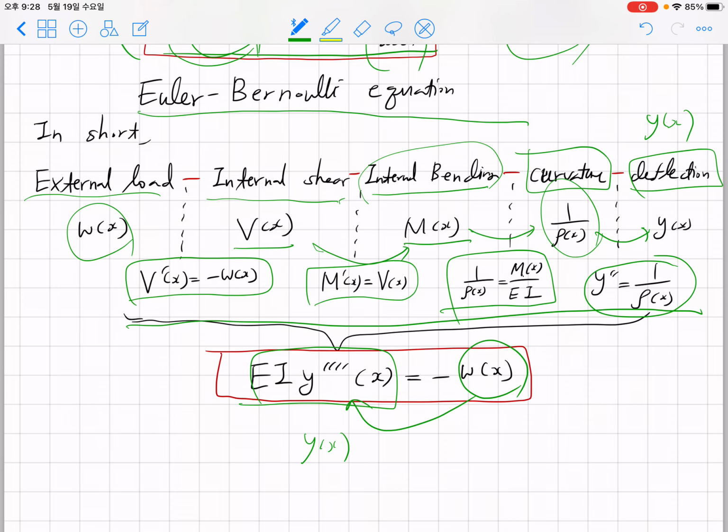However, even though you have taken some lessons until now, you're still going to feel a little bit unsatisfied, because we learned that M would cause normal stress, and out of normal stress you can expect normal strain. However, when we learned about shear force, shear force somehow induces shear stress, which can be obtained as VQ over It.